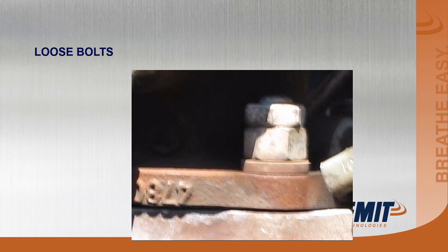Okay. Here's a common place. You've got a gasket that's missing down here. It's been blown out. And in this particular one, this stud was broke off, and you could pick that nut up out of the hole. It's never fun to repair these, but it's critical that these are repaired for the performance of the catalyst. A leak like this would cause a failure as far as emissions reduction across the catalyst.